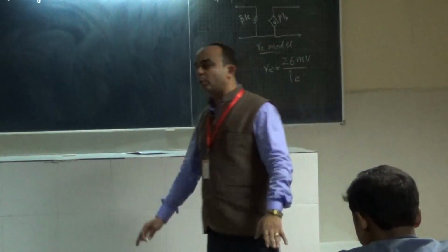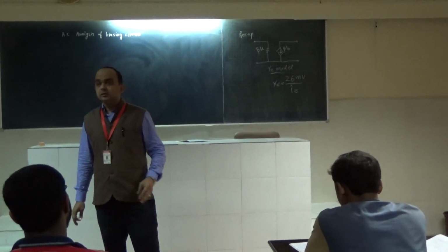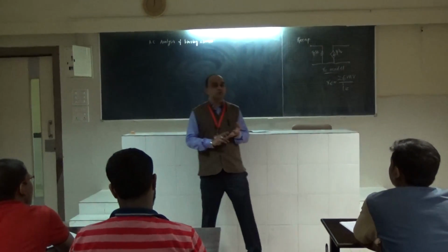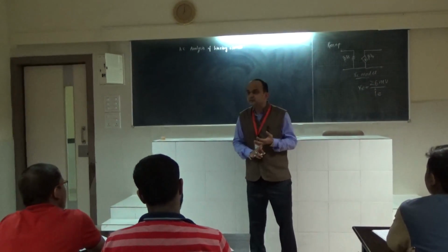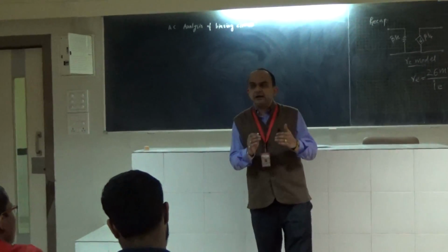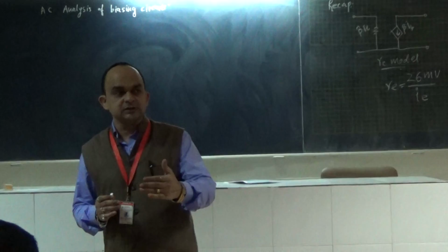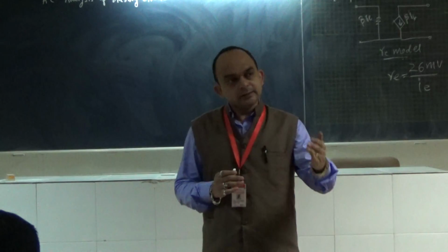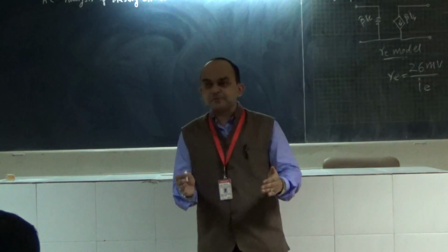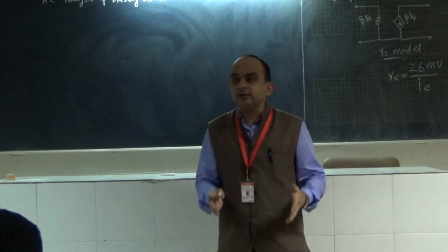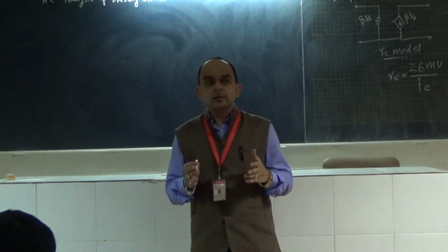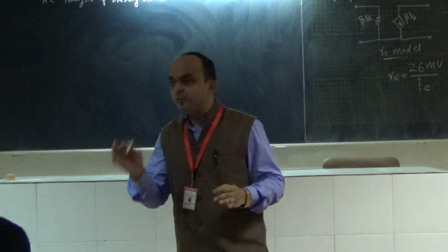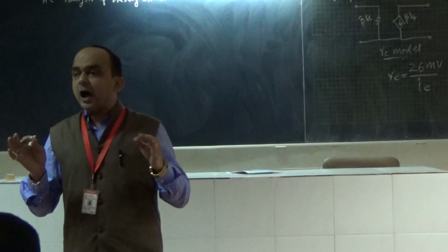First, again you tell me what all the different biasing circuits are. Fixed bias, self-bias, collector to base bias. Which one is most widely used? Self-bias. But since my strategy is always from simple to complex, I will take one fixed bias amplifier circuit first. Then I will show you the steps. The most expected question in the exam as per your syllabus is common emitter configuration with self-bias, RE analysis.